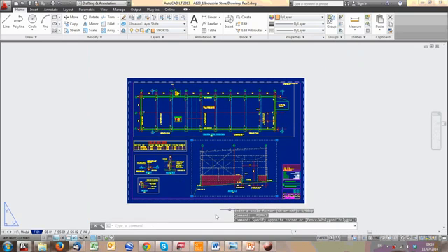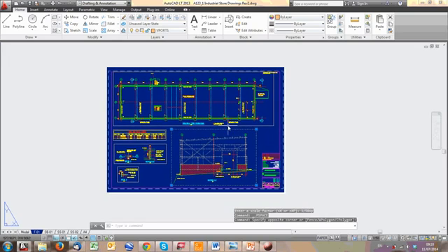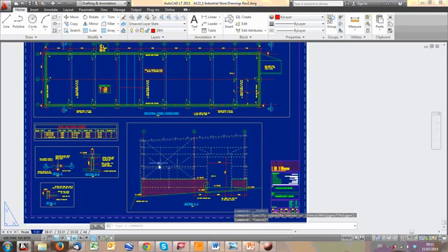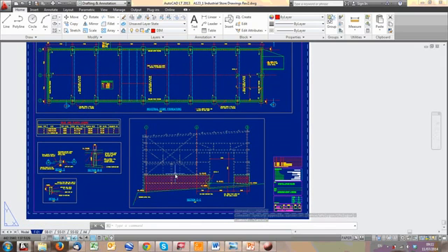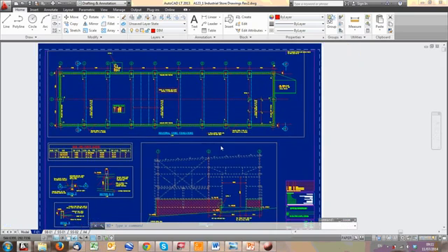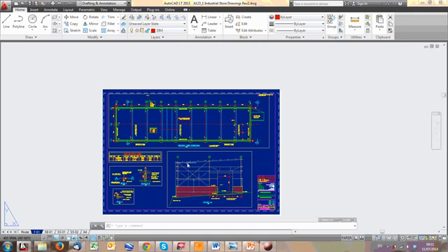Alright, what I've been doing was in the command window, and we're going to have a look right now at the commands and the ribbons at the top. But before we finish that, let's just finish up with looking at viewports. Viewports are windows into your model space, and normally with a drawing you want to set it up at the beginning such that your viewports are there. You know what you're going to put on the drawing, so you know what scale they have to be.